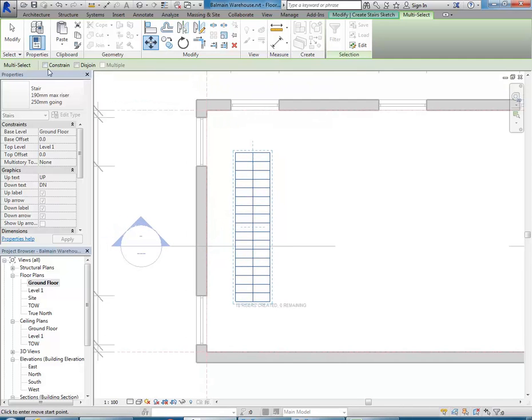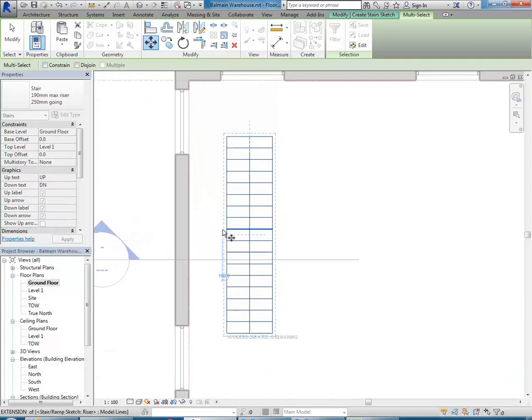I'll come and have a look at it in a minute anyway, so this is the final thing. So then to force it to get the midpoint of this edge on the side, I'm just going to show you a shortcut, SM. If you type SM, which means snap to midpoint, then you can move onto the edge of this sketch on the left-hand side, and notice how, as long as I've highlighted that edge there, it'll give the triangle, which is our symbol for midpoint, so we know that we're picking up from that point.